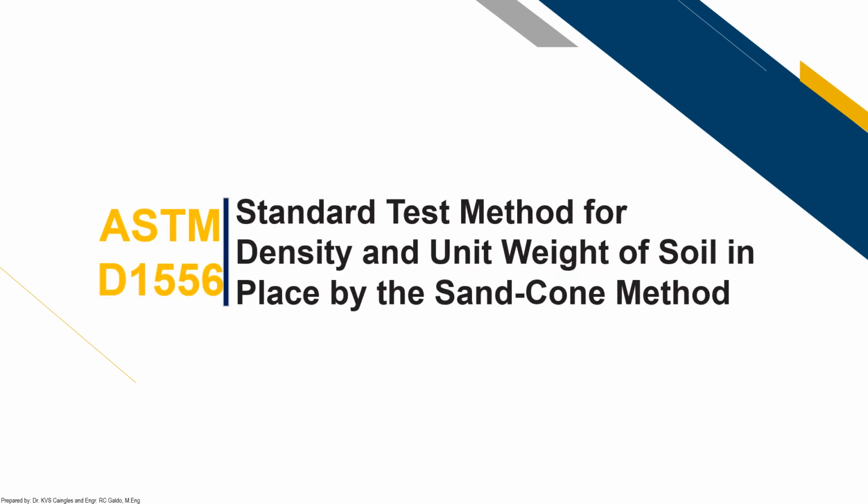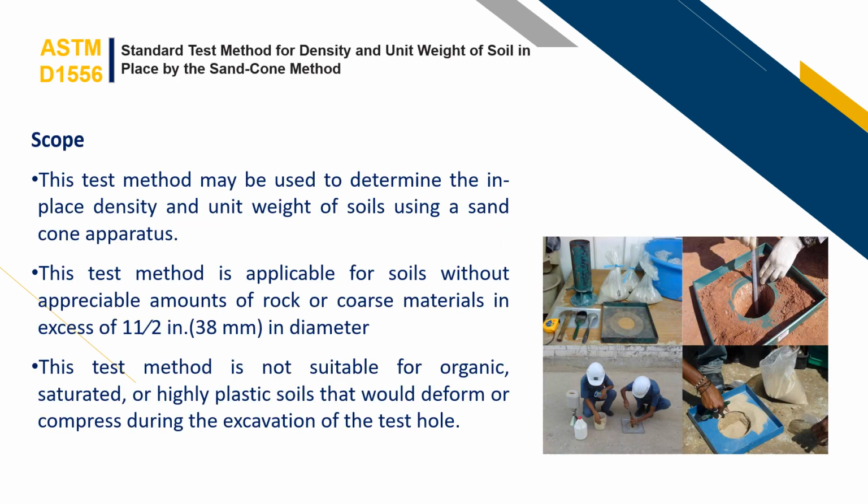Now, among all those tests that cover the field test for soil, we only pick one, and that is what we will discuss. First we talk about the field tests for soil. So among all those tests, we have ASTM D1556, or the standard test method for density and unit weight of soil in place by the sand cone method.